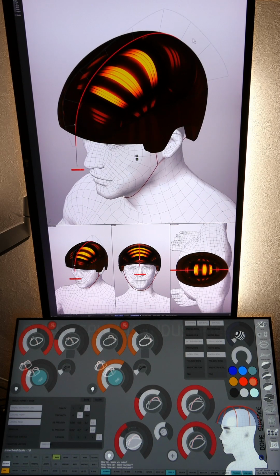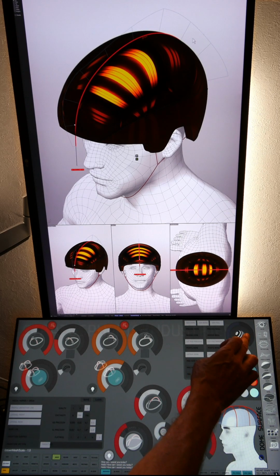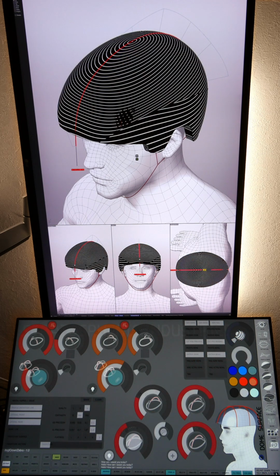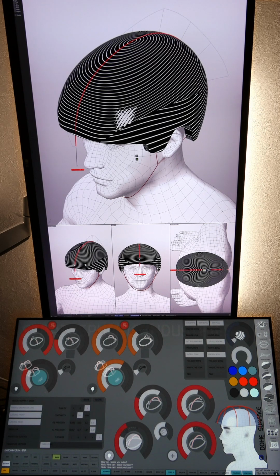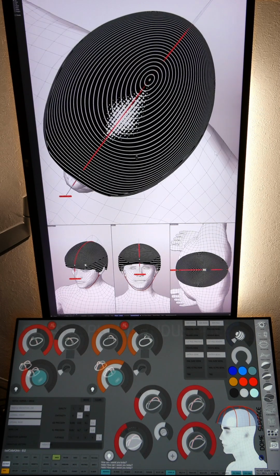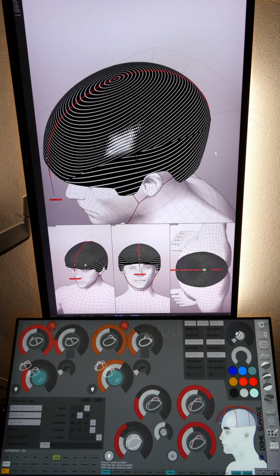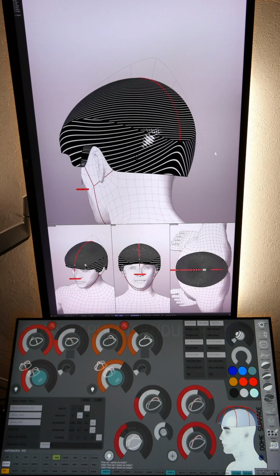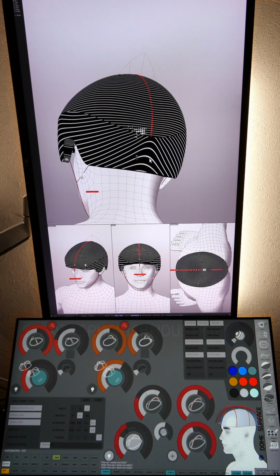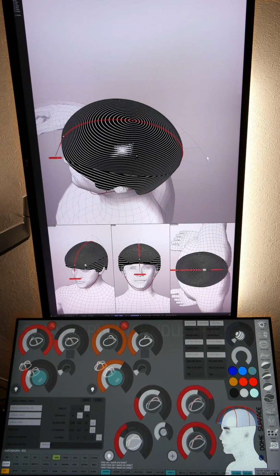In addition to the different kinds of rendering materials, there's also a zebra-esque isophote display. This allows for seeing the curvature. It's not exactly like a zebra, which always rotates according to the view. But this shows the actual curvature of the shape, distancing of the curvature, where the spaces in between the lines are wider. That's a flatter curvature. You can tell the evenness of the set of lines as it goes across.